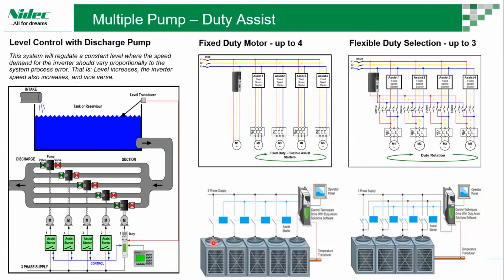So here, this is one of the cooling towers we can see. This is one drive, one motor. Just imagine, what will happen if you are running all the fans at the same speed? Then imbalance does not happen on the mechanical part. So the mechanical stress is reduced if we are running every motor at the same speed.